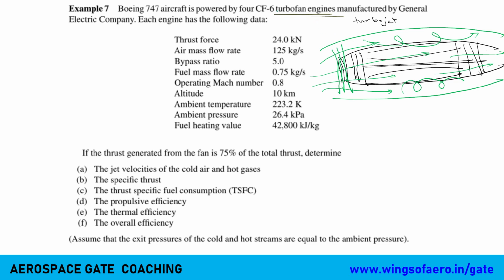So from here, for this turbofan, we have a bypass ratio. The larger the fan diameter, the higher the bypass ratio. And if the bypass ratio is high, it helps better mixing of air and fuel, so combustion is better. As combustion is better, it reduces SFC, and obviously that will improve the efficiency. Can you connect all this together? Can you follow this relation?